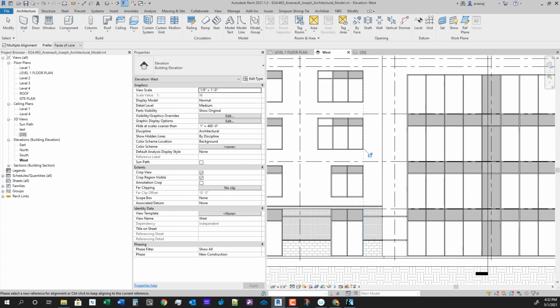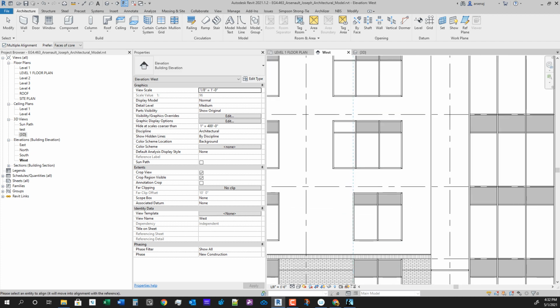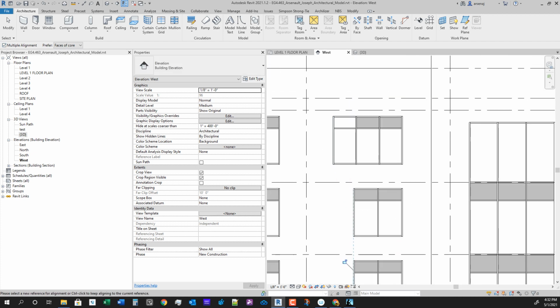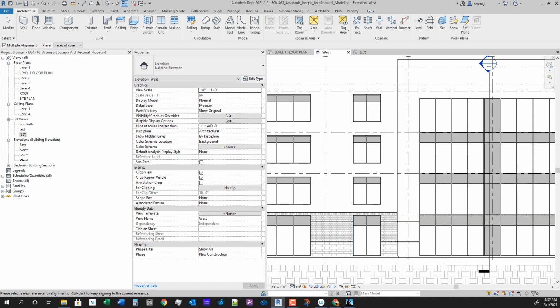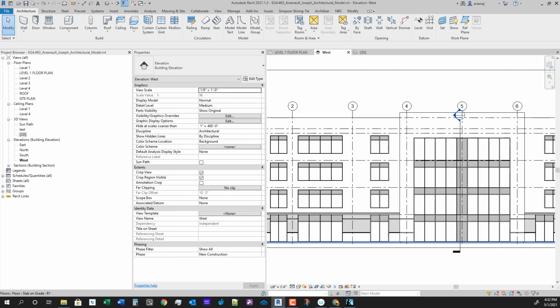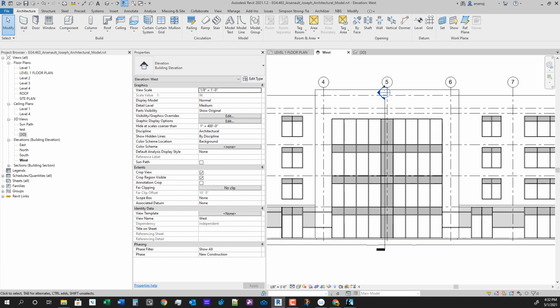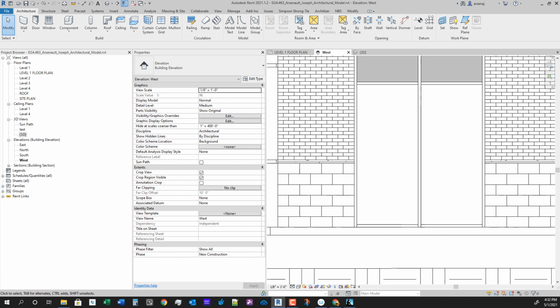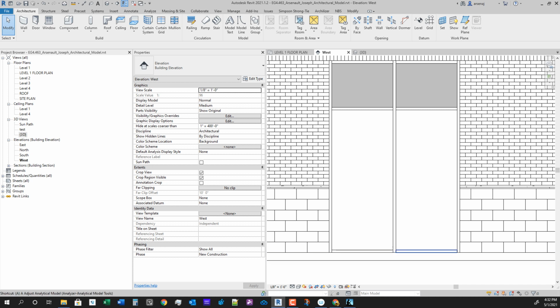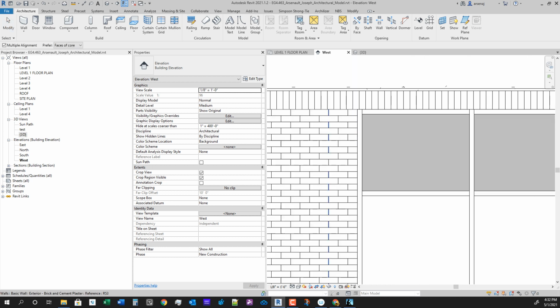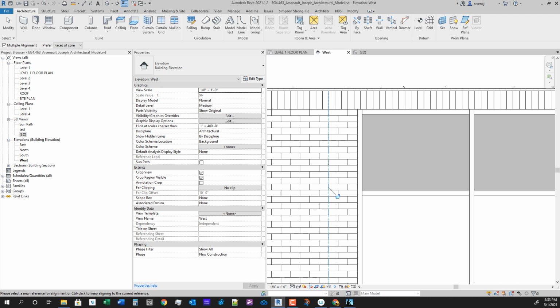And so right now I'm going to have to hit escape and then get back into the align command, because it'll still be multiple. If I would have tried to align those other sides, it would have tried to align it with the other edge we were trying to align to. So with your align multiple on, just remember, I'm only going to align this one thing, so I need to hit escape to get out of that.